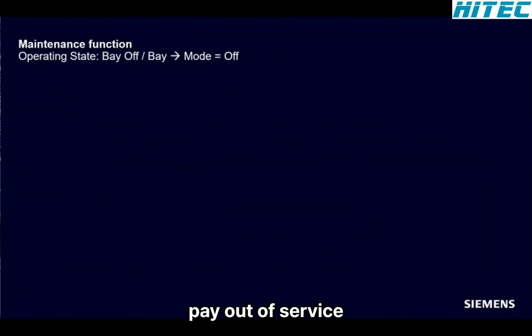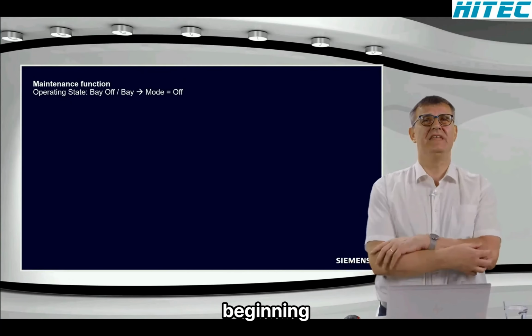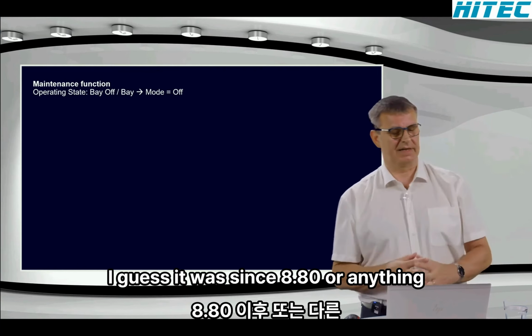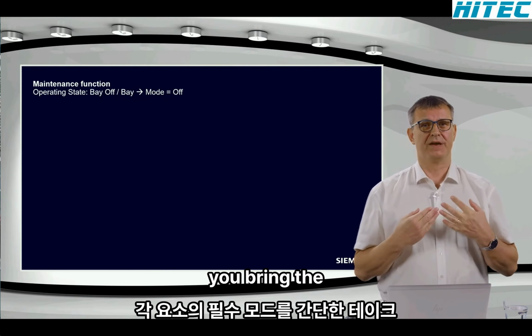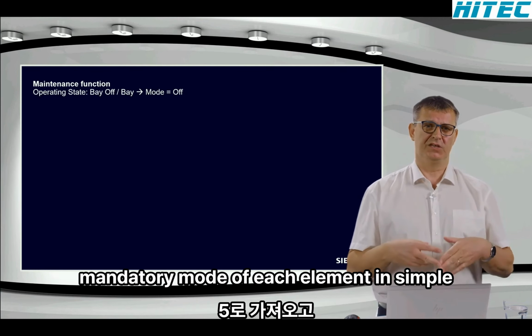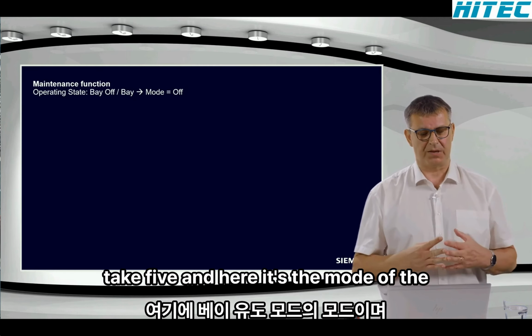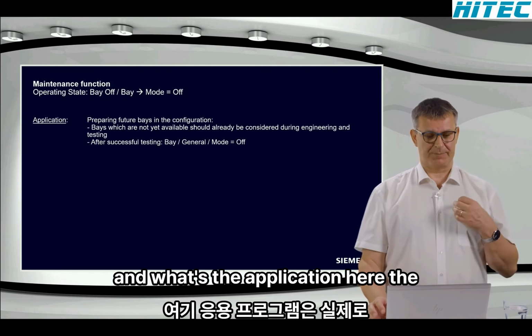Bay out of service. We also have, not since the very beginning, I guess it was since V8.80 or something else, this functionality bay off, where you bring the mandatory mode of each element in SIPROTEC 5, and here it's the mode of the bay, into the mode off. And what's the application here?